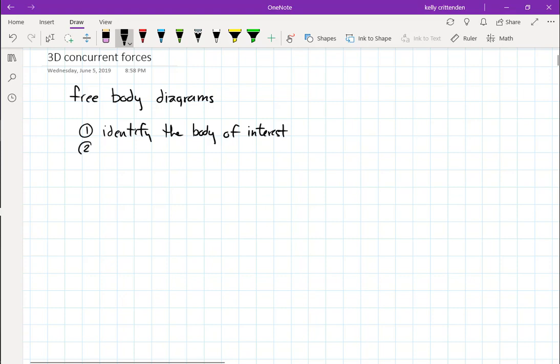And then I'm assuming that you've got some figure drawn, not a free body diagram, but a picture, or maybe you've envisioned the thing in the real world. But assuming you have a picture of the thing, then just draw a circle around this body. What this will do is, unless this body is floating in outer space, in which case it already is a free body, drawing a circle around it will force you to draw through whatever it's connected to.